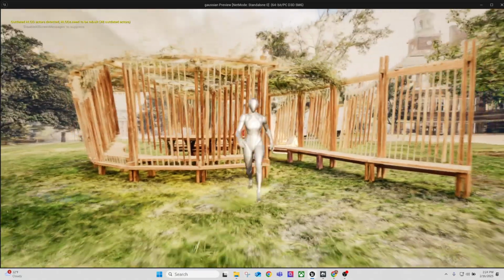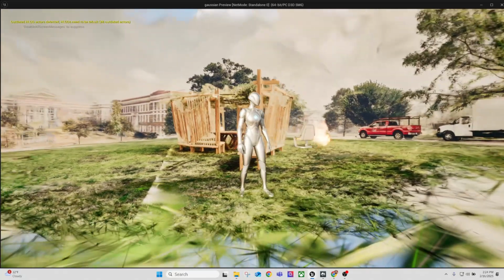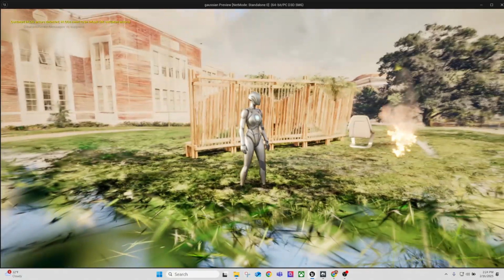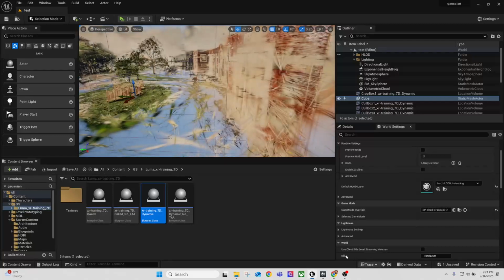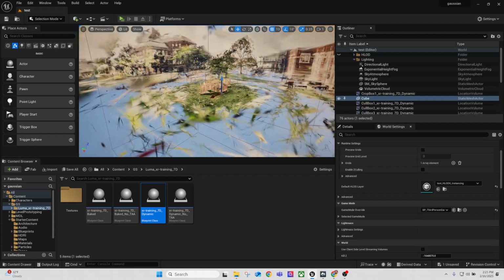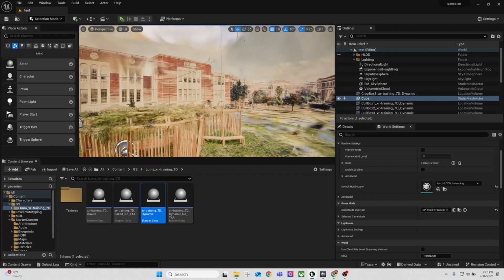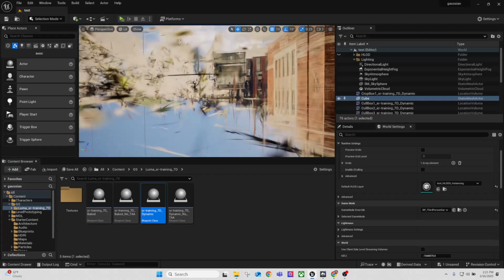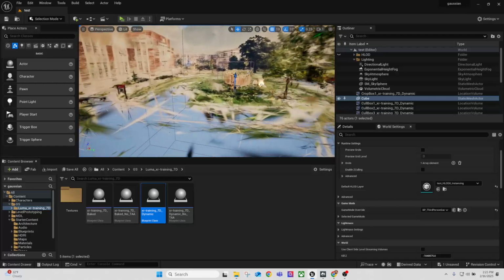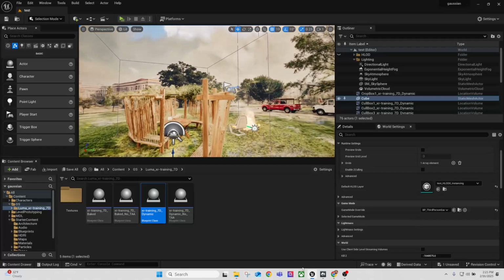So that's the whole process, from capturing a sequence of images, into the training program using PostShot, and then exporting the PLY file into Unreal. Then you can set up the 3D. You can see that the further away from the middle, the more noise there is, but it captures a pretty good way of understanding the dimensions and the distance. So I highly recommend you try it.